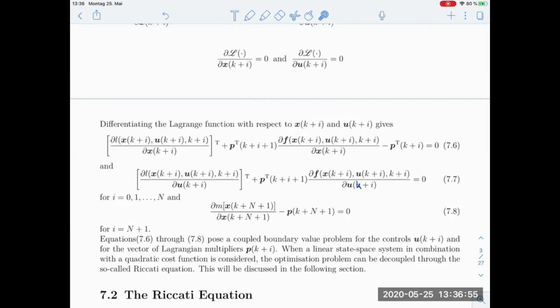So all these equations are a lot of relationships that we have to fulfill in order to be optimal in our control problem. But the point is, these derivatives are typically simpler equations, simpler in structure than the original problem even. So for example, if you have a quadratic form, as we will have afterwards in the concrete optimal controllers that we will look at, we have some quadratic control error, for example. So this L could be a quadratic function. And then if we derive a quadratic function, which is quadratic in x, with respect to x, we will end up with a linear function.